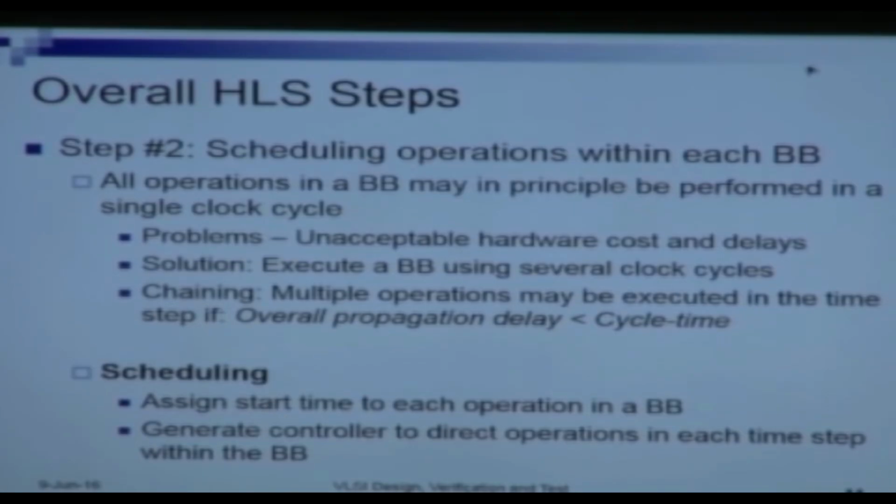So all these will have to incur this delay, and there could be very small basic blocks as well. All basic blocks will not be this big. Because we have said that all operations within a basic block will take only one clock step, whatever the size of the basic block, small or big, we will do it in one clock step. So there will be many small basic blocks which will very quickly complete their operations and just sit, because the big basic block takes just one clock cycle, and hence the length of the clock cycle has to be big so that all these operations can be executed within it, and many basic blocks will sit idle after completing all their operations. And hence it is not advisable to do many operations within one clock step.